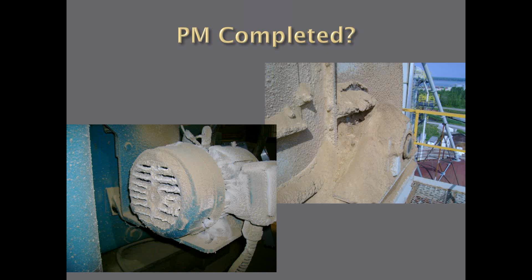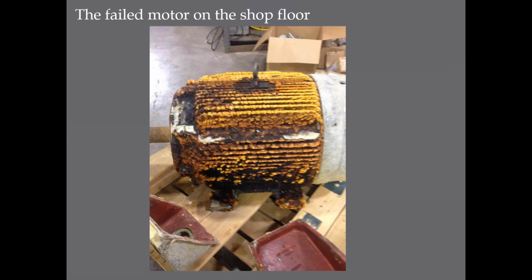But what we ended up doing here, because of high winds, cold weather in this area, it gets to minus 20 in the winter, I put an automatic luber on here, a battery-powered automatic luber, to make sure this PM task was always completed, so this bearing doesn't fail.